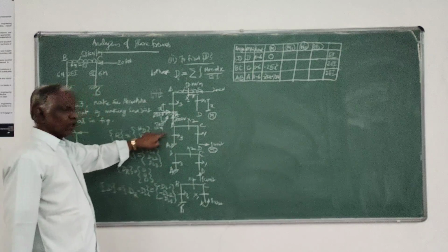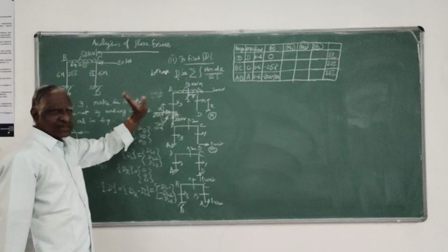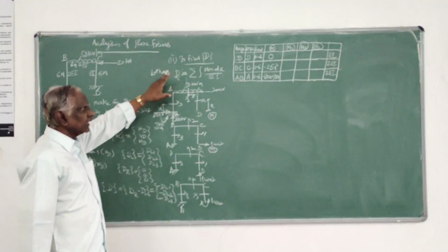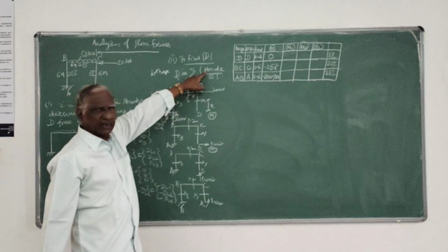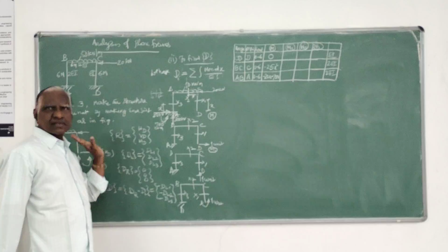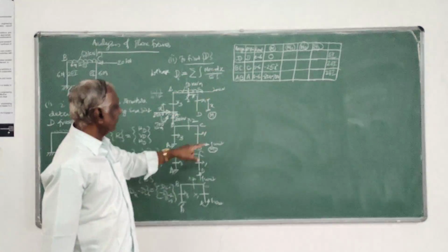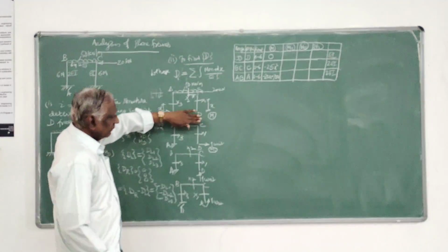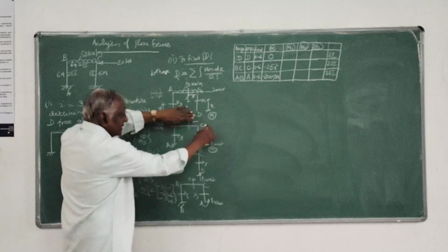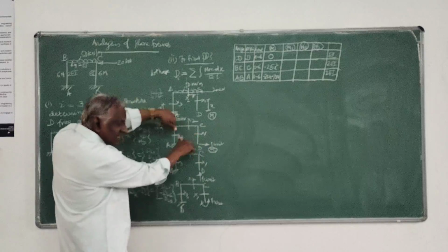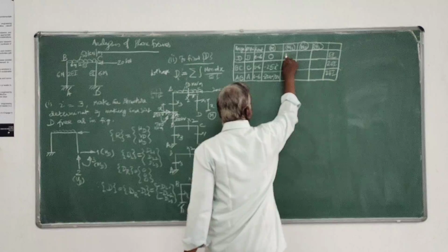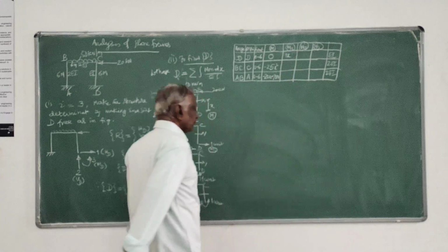Now coming to the M1, on the same lines, we have to find the same sections covering the entire structure, the moments, capital M and small m, in order to work out these displacements. So coming to M1, same thing: moment about x1 is 1 into x, giving a moment like that, inside sagging, positive. So it is 1 into x positive.